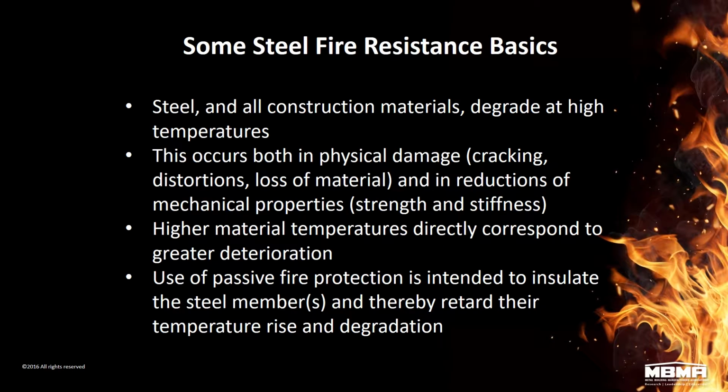Some fire resistance basics that will be used throughout the remaining parts of this presentation series. Even though steel as well as concrete and masonry are all identified as non-combustible materials that don't ignite and burn, all materials, including the non-combustible ones, will degrade at high temperatures. This degradation can be of two forms.